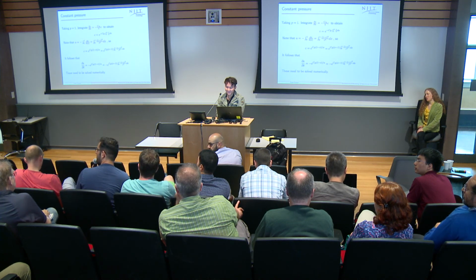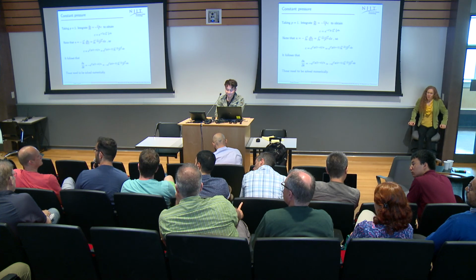So basically, when we consider, let's say, absorption and blocking by big particles, we don't consider that the blocking by big particles happens completely, in the sense that the particle comes and sits on top of the pore, and still we have leakage underneath. So even if the pore is blocked by big particles, we can still have absorption there. That's why we are adding them. And also, we didn't consider cake here. Cake was studied in a lot of literature, not a lot, but quite a lot. But the point is that people in industry, I guess, don't like that mode, in the sense that when the filter is almost clogged, they prefer to throw it away and get a new one. Great. Any more questions?